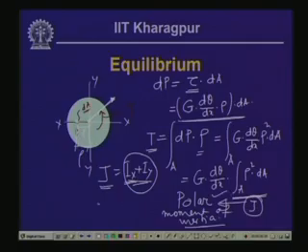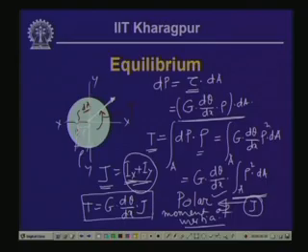So, this particular expression for torsion then is equal to G times d theta dx times J. Now, let us evaluate the rotation over the entire length of the bar. We have seen that the twisting moment applied is related to the rotation per unit length in terms of the polar moment of inertia of the section and the shear modulus. If the bar is fixed at one end and subjected to a twisting moment on the other, what is the change in the angle, or the change in rotation, over the entire length of the bar?